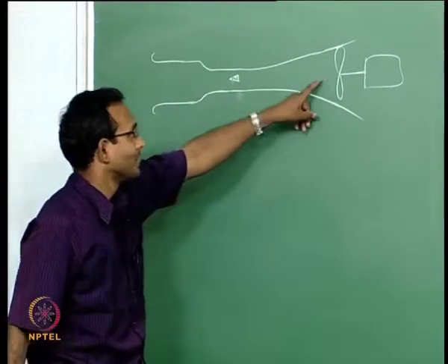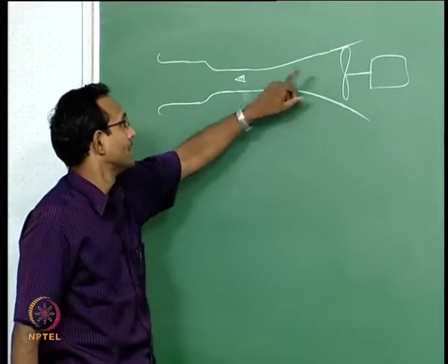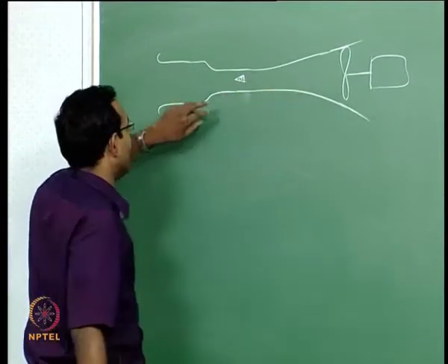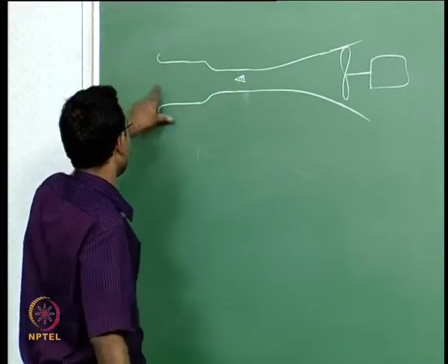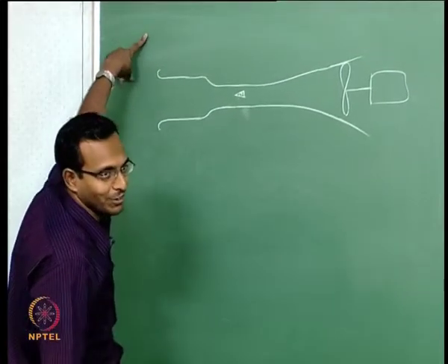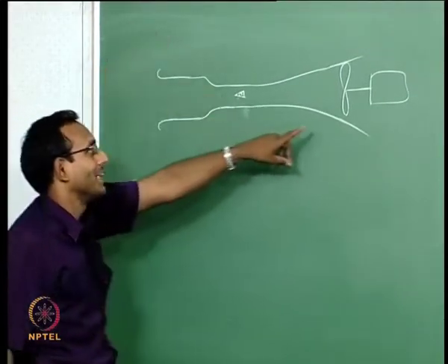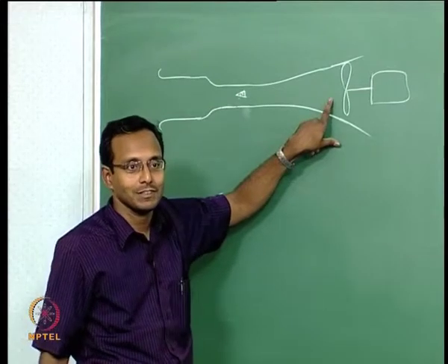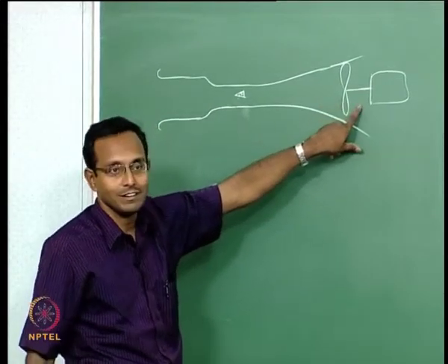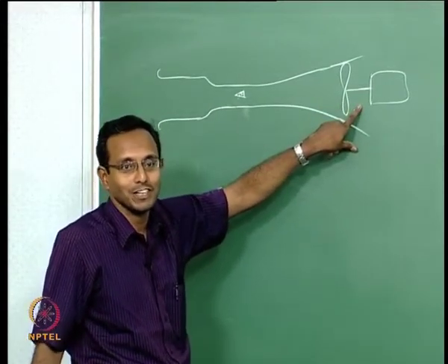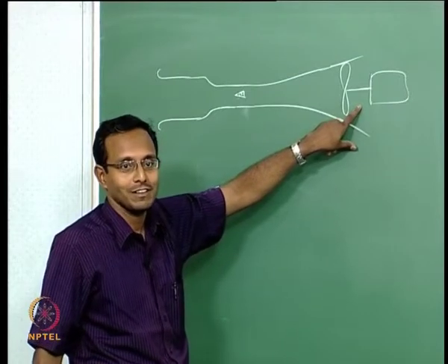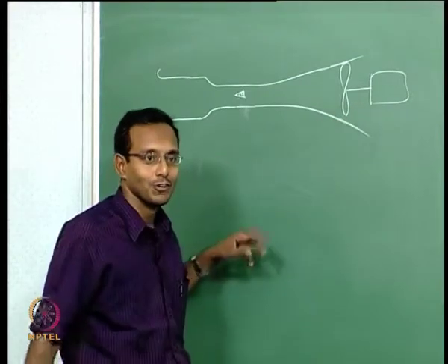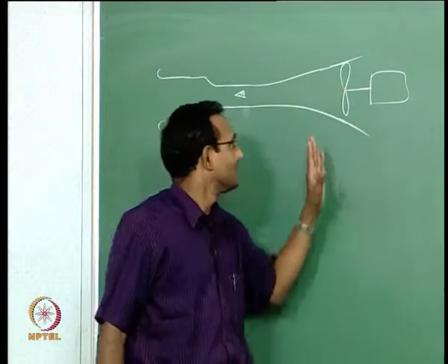I will cause suction here in the diffuser section. I create suction, and that is going to start the flow from here. P naught is atmospheric, it is an in-draft tunnel. Another way of creating an in-draft facility for low Mach numbers is to just use a fan, up to 0.6 or so. Above that I need to go for actual vacuum pumps and storing this.